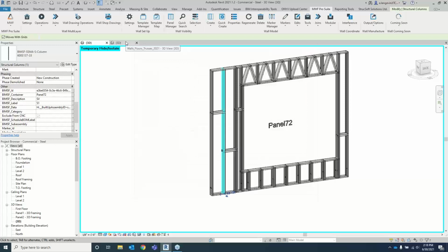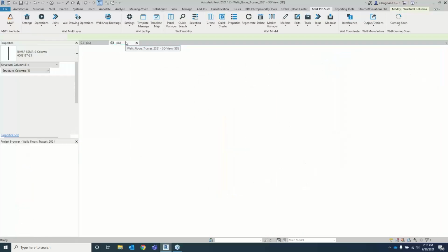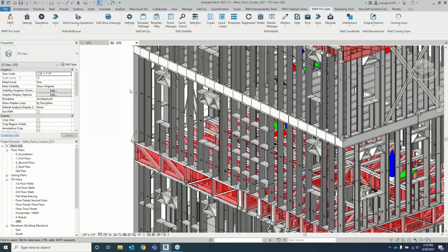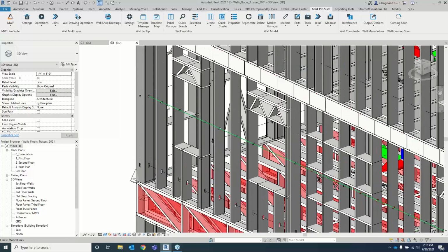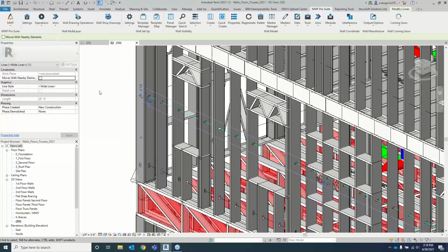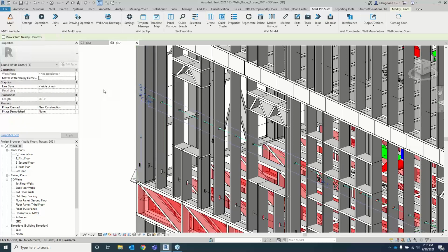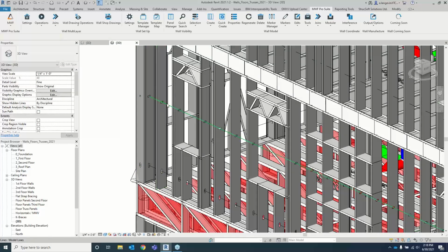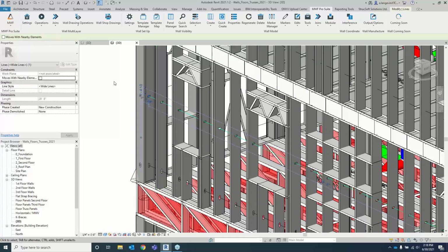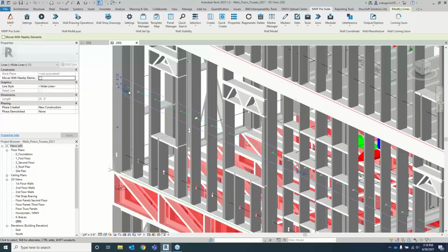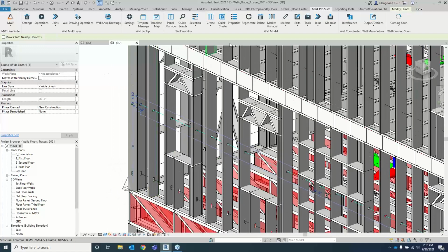And now we're just going to swap over to my other project. In this project, I've already designed my model lines. Okay, so this is what we're going to be using as marker lines, which we're then going to convert into our hole series. So make sure that you're using the 3D model lines. This won't work with detail lines and such. Okay, so once these are placed into your panel, you'll notice the holes are already there, but we're going to go ahead and change these up a little bit.